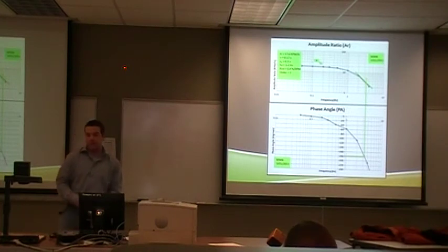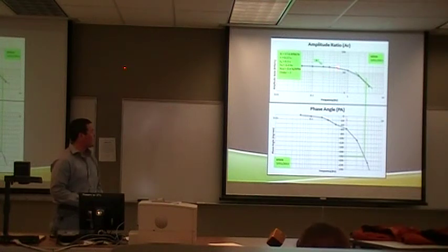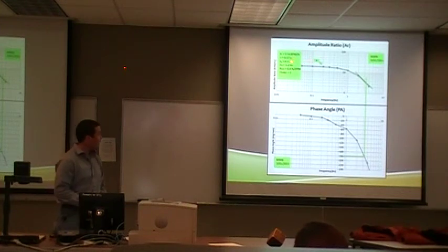We varied the frequencies in the sine response, and we're able to come up with a Bode plot. In the Bode plot, we get the K by the asymptote here, which was about 17.6 RPM per percent. The tau, we got at 0.7 seconds, which we get from the amplitude ratio equation, and we analyze it at the frequency at point A here.